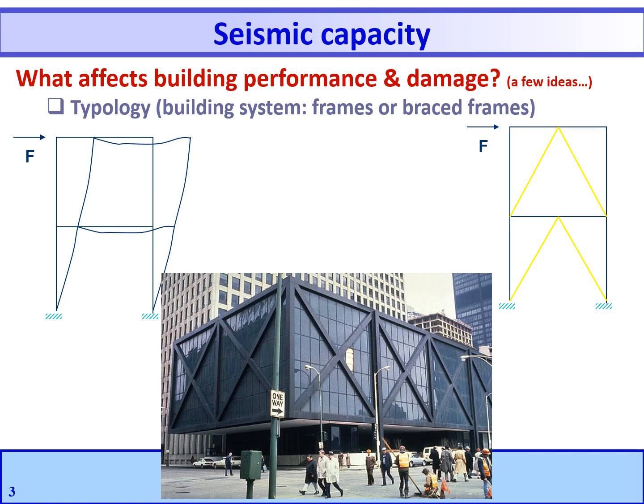The third one would be to resist a moderate level of ground motion without structural damage or only some non-structural damage. And finally, when we have a major event, our structures need to resist a major level of ground motion, having an intensity equal to the strongest either experienced or forecast for the building site, without collapse, but possibly with some structural as well as non-structural damage.